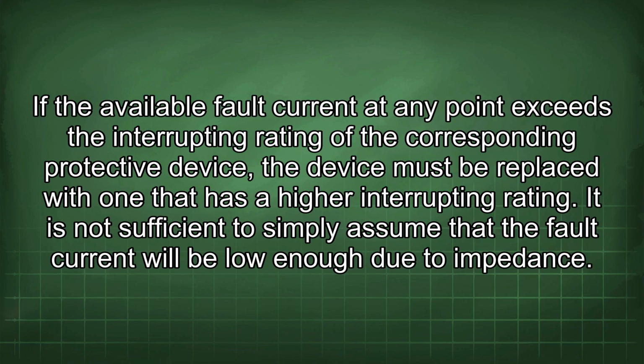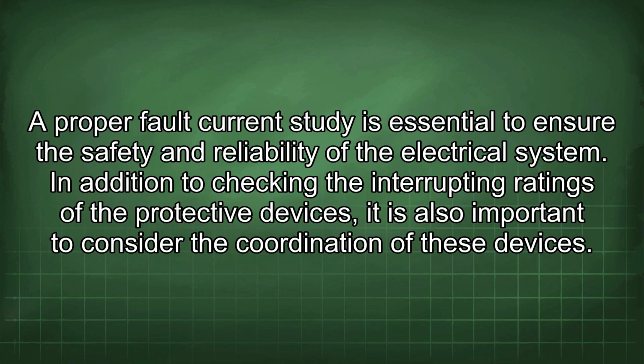If the available fault current at any point exceeds the interrupting rating of the corresponding protective device, the device must be replaced with one that has a higher interrupting rating. It is not sufficient to simply assume that the fault current will be low enough due to impedance. A proper fault current study is essential to ensure the safety and reliability of the electrical system.